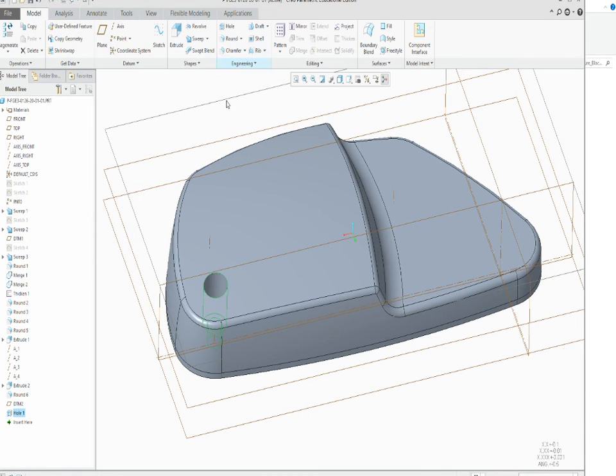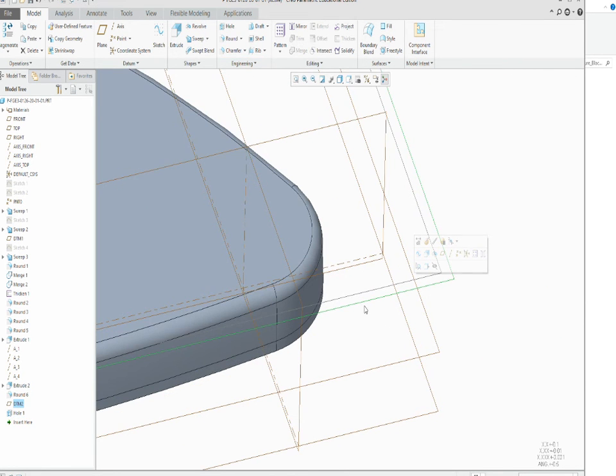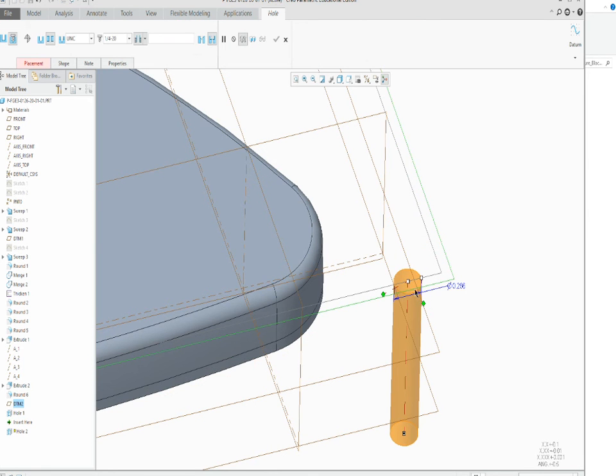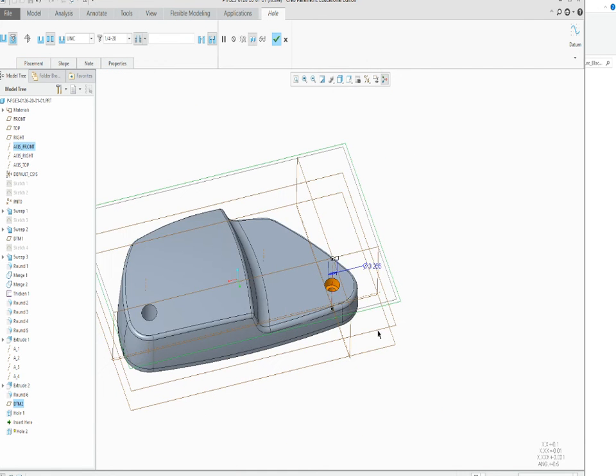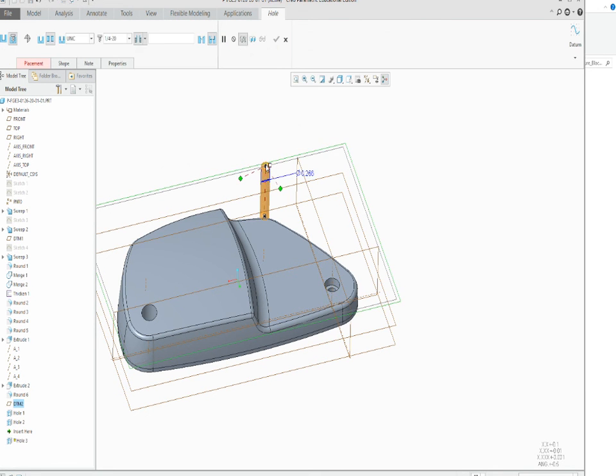Now we say OK, we hit Control C, we grab this plane again, we go Control V as in vector, we drag with Shift down, and then we drop it on that axis, and you're going to see the hole come into place. Do the same thing again, Control V, and then we drag and we hold Shift and we drop it on that hole.